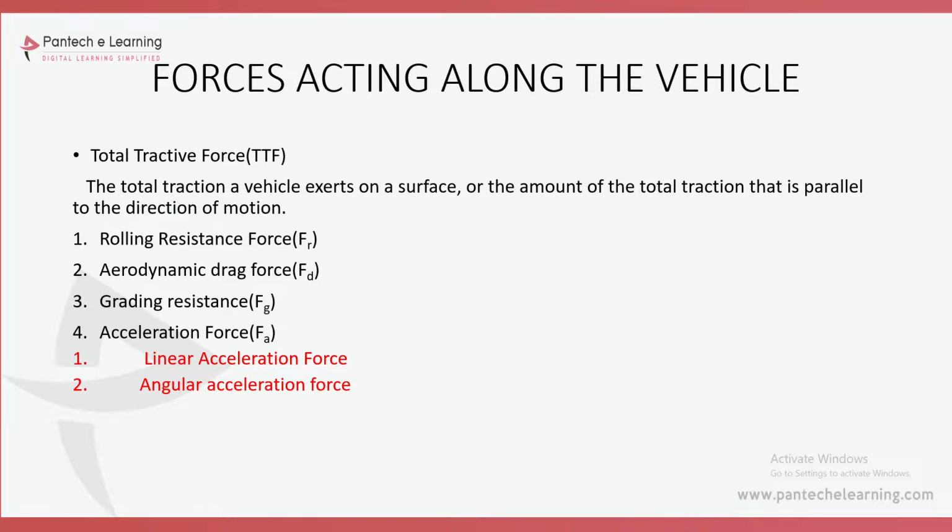Now, the force acting on the vehicle. The total name is total tractive force, TTF. We have TTF classified into four types. These are all the forces acting along your vehicle while driving: rolling resistance force, aerodynamic drag force, gradient resistance, and acceleration force. The acceleration category is of two types, linear acceleration and angular acceleration. These are all the forces acting along your vehicle.